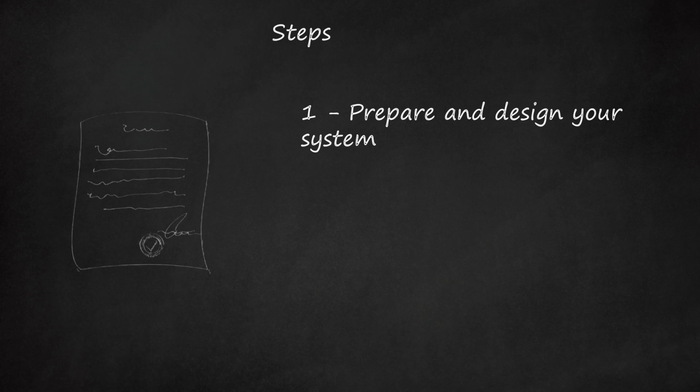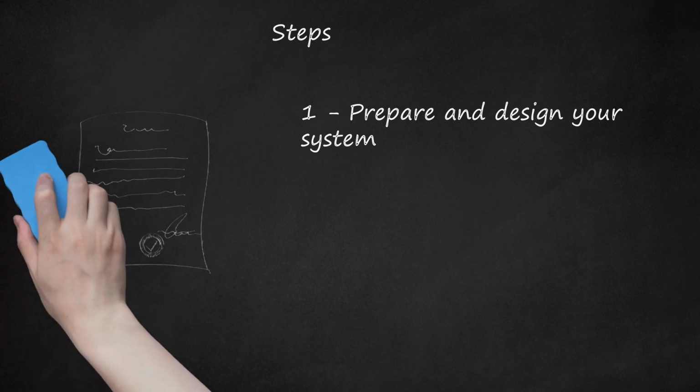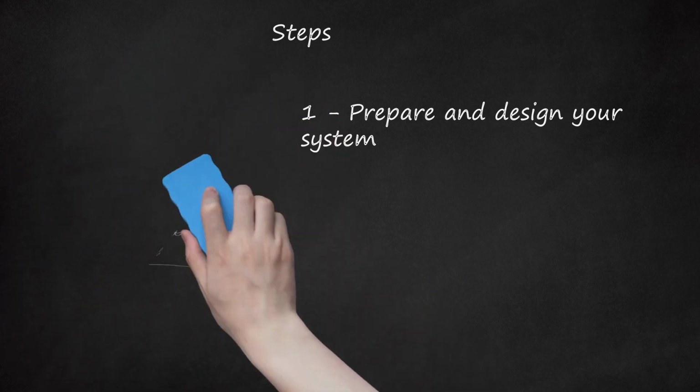Site survey findings that influence the design include things like available space, topography, intended purpose and perceived water use based on the size of the building the system will service, location of the well and/or neighboring wells. Soil test findings that influence the design include things like soil type and layering, sand, clay, rock, and where it is located relative to depth. Ability of the soil to drain and filter wastewater.